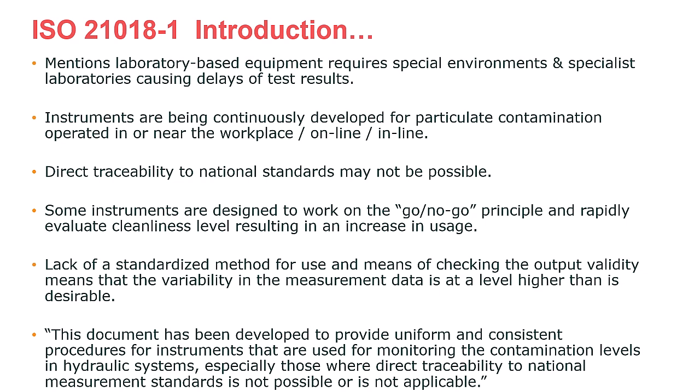I do mention here in quotes the fact that the instruments are being developed for contamination monitoring, but again, in hydraulic oil, may not be tested to be traceable to national measurement standards. And that's where it keeps on referring to ISO 11171.